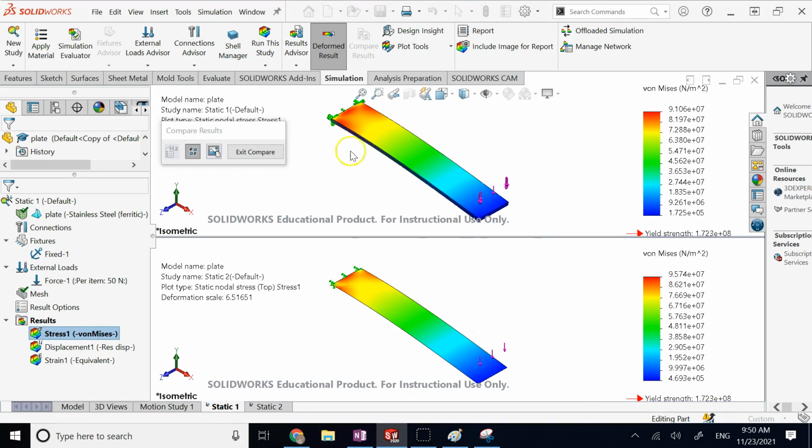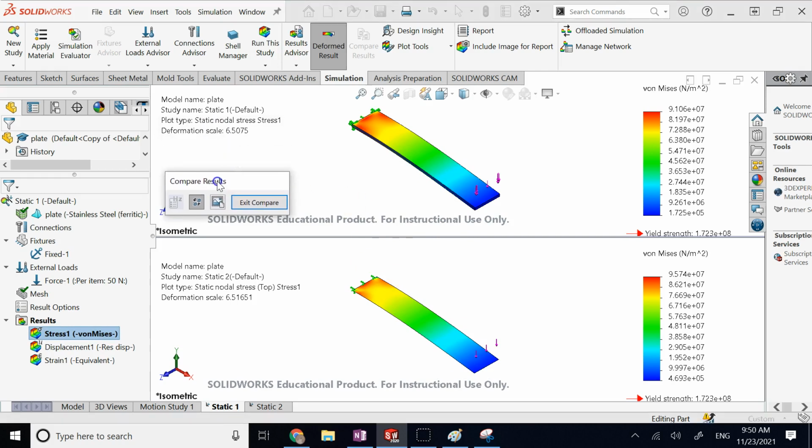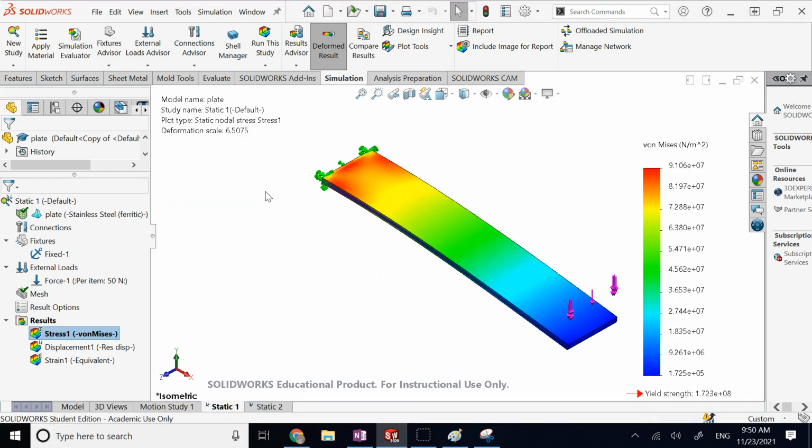And now if you look, you see a huge degree of similarity and quite similar numbers, not exactly the same, but very similar. So anytime you simplify, you're going to lose a little bit of accuracy. You're not going to get the perfect equal thing, but you clearly see going from 3D to 2D made very similar results. So this is using a shell instead of 3D elements, okay?